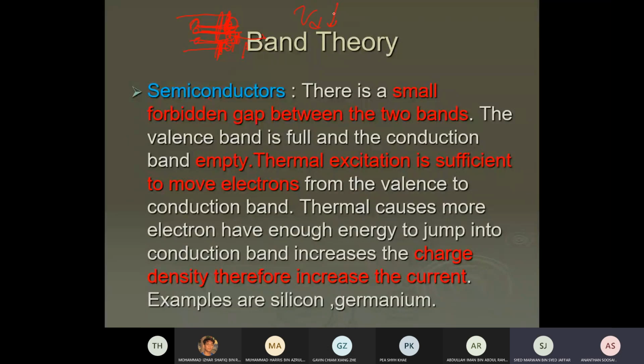So drift velocity decreases, but the charge density increases, meaning there is a sufficient amount of electrons that it is enough to increase the current. Yes, that's what you have said. The increase in charge density outweighs the decrease in drift velocity, therefore current increases.